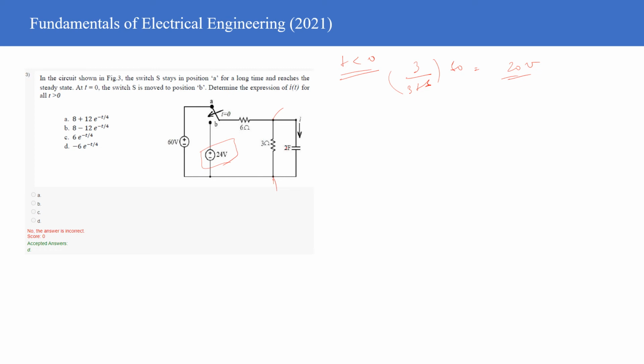and this will be the initial voltage of the capacitance, right? Now what you're doing is that you are just turning this particular switch to position B, right? So at position B, you will do again the same thing. You will write the KCL at this particular point, right? So let me assume the potential at this particular node as a function of time to be voltage V, right?